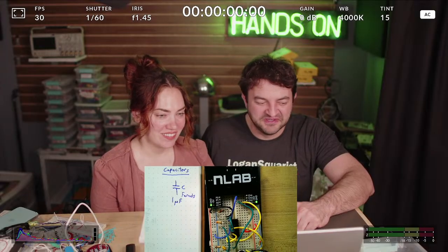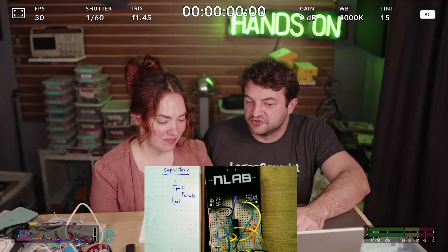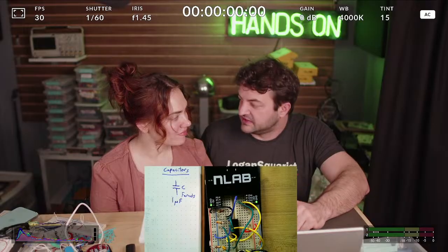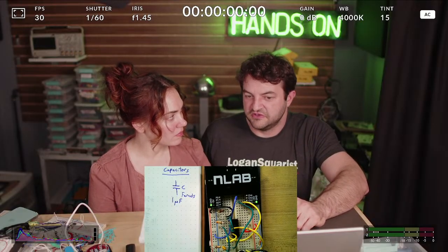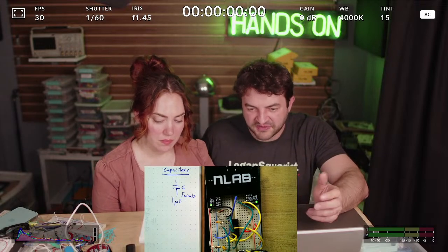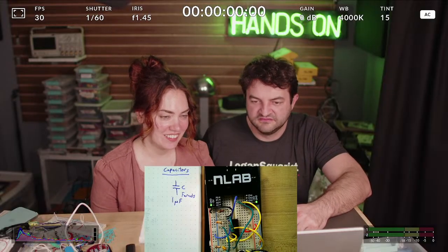Yeah, probably fascinating details into capacitors. Also, the aluminum capacitors are usually polarized. So if you ever see a capacitor where one leg is longer than the other, that's because if you hook them up backwards and apply a big voltage, they will explode. Or not explode, but they'll kind of pop and this goo will come out. But these are not like that, right? These are not like that, yeah. Thank goodness.